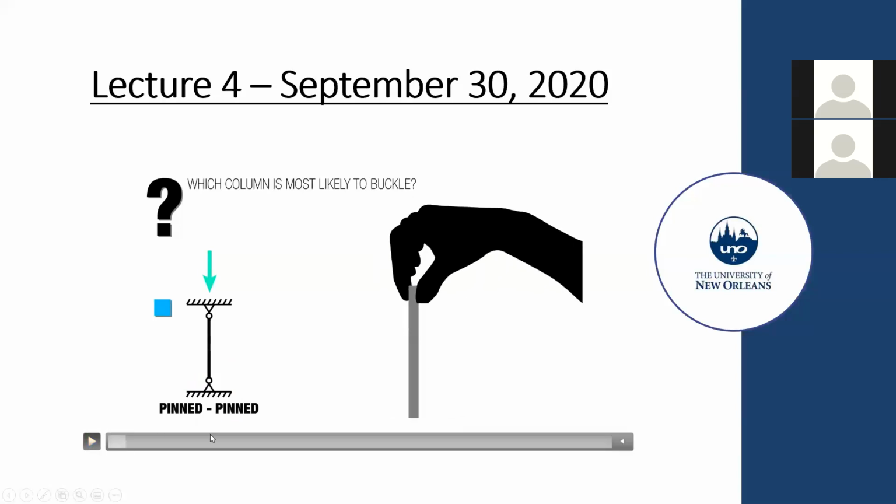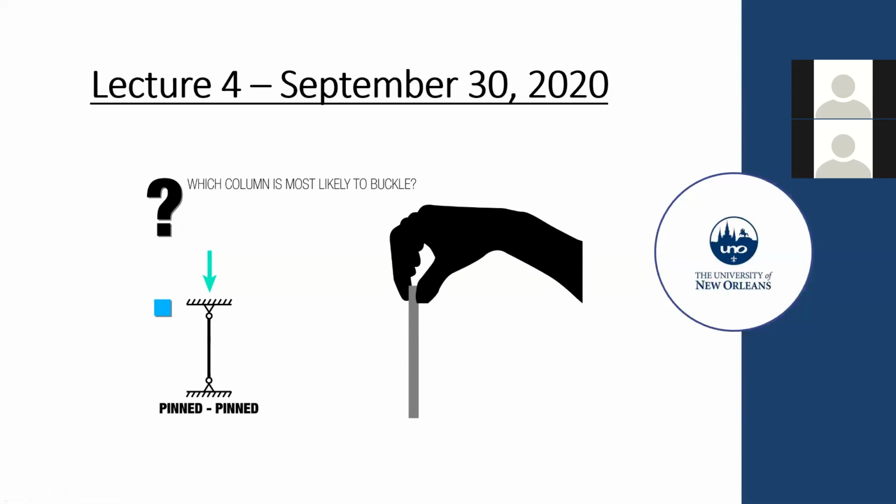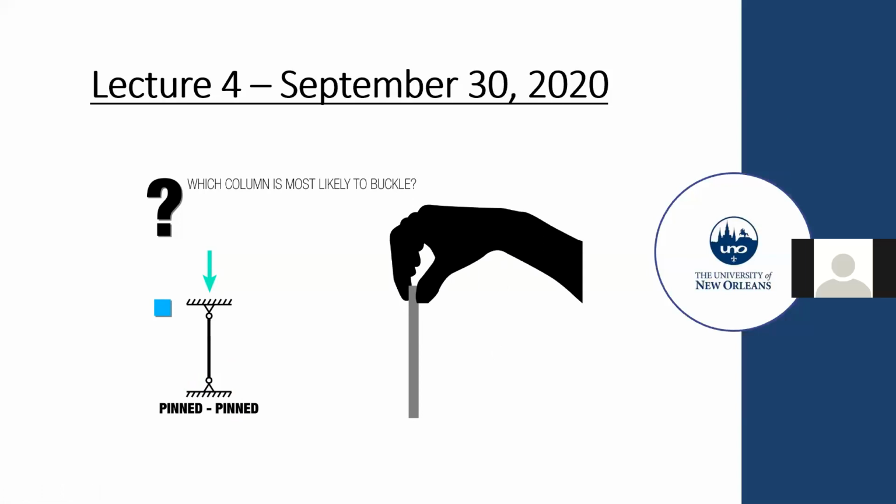So this rod is able to rotate, there is no fixed connection at the top, but it cannot translate, it cannot move in the X direction because I'm holding it, right? As opposed to holding and grabbing it in my fist. If I hold it like this, how is it going to move, how is it going to rotate? And if it's fixed at the bottom, there's no way to move and rotate. These are different types of connections. The first one is pin-pin.